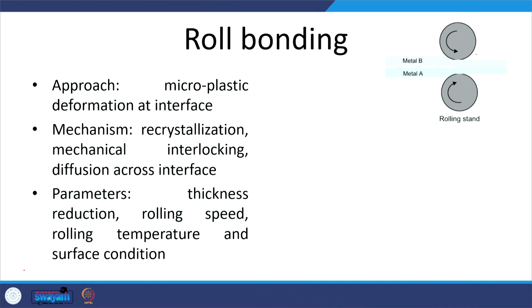So, how is the bond developed? Like say when the rolling happens, there will certainly be some kind of heat generation. Okay. If the rolling speed is less, whatever heat will be generated will remain at the interface, but there will be more bonding time, like 2 sheets will be there under pressure for a longer time when we use the lesser rolling speed.